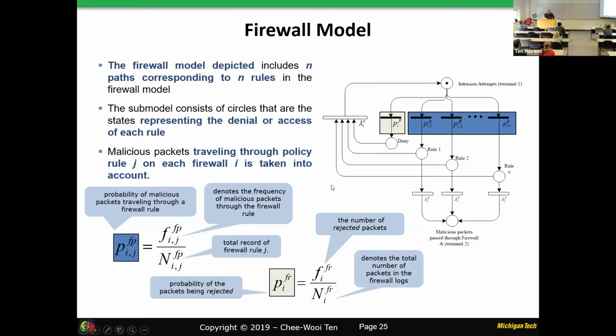So we start with the modeling of the cyber aspect. As you can see, this is a cyber-physical problem, right? You have a cyber intrusion that will successfully hack into a system. What we want to do is capture the existing deployed cybersecurity technology in substations, which includes firewalls, and in this case we use a stochastic Petri net to capture that. The rule is that in the OT network, we simply deny everything and then specifically allow certain ports to go through, unlike in the IT world, where it's the other way around.